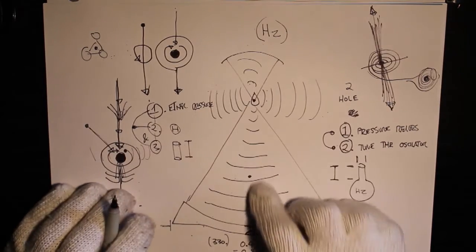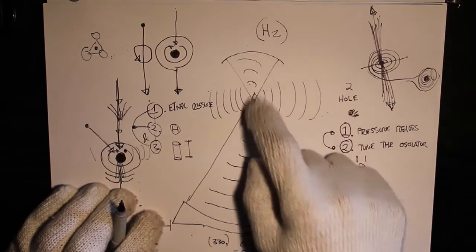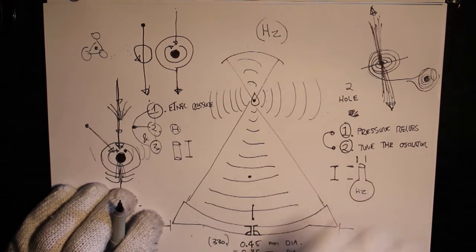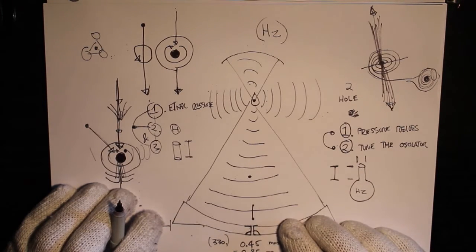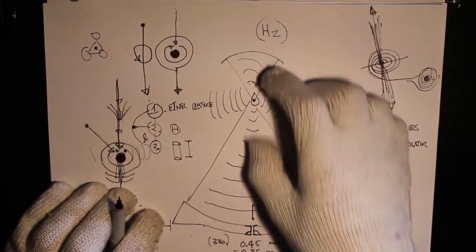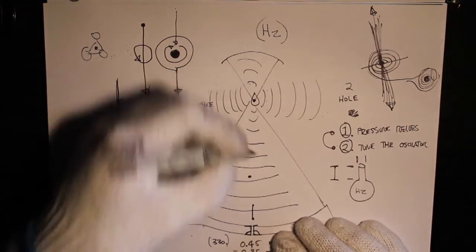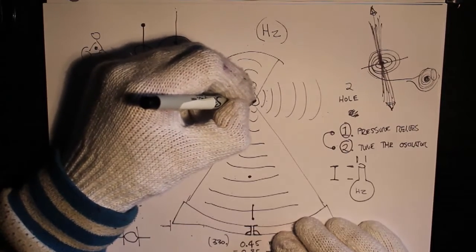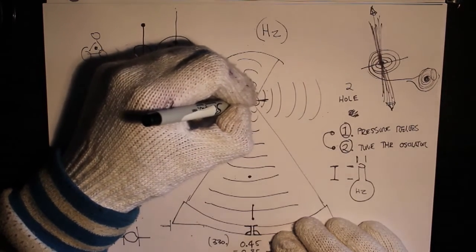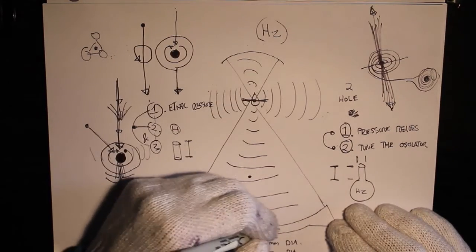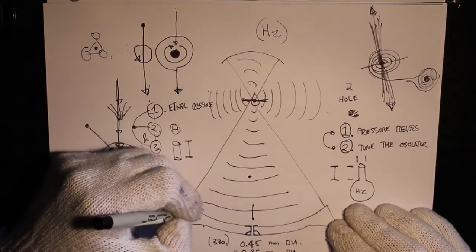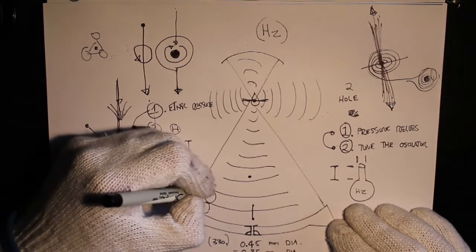and how the cavity, to look at it as an analogy, it's not quite the same, but it works similar to a Helmholtz Resonator, where you blow on a bottle and it makes that tone. It's similar in the way you tune it, but it's not similar in the way the waves pass through it. So you've got your standing waves running from the center, the focal point of the crystal, to the bottom of the reflector. And standing waves are nodes and antinodes of pressure.